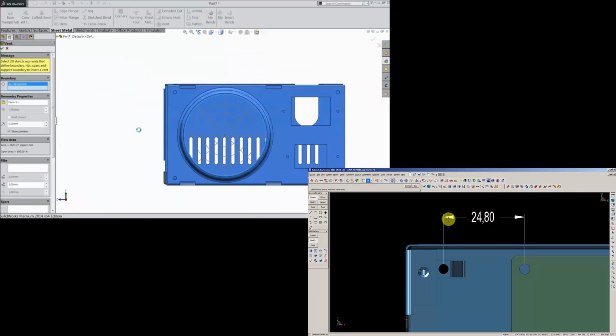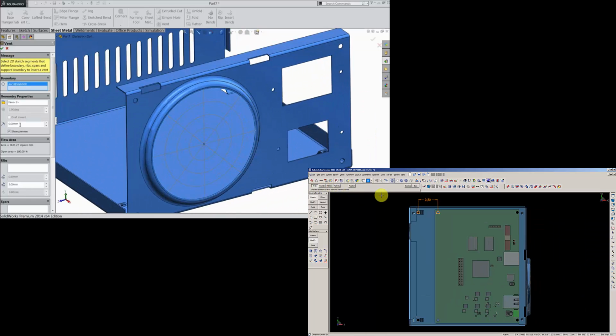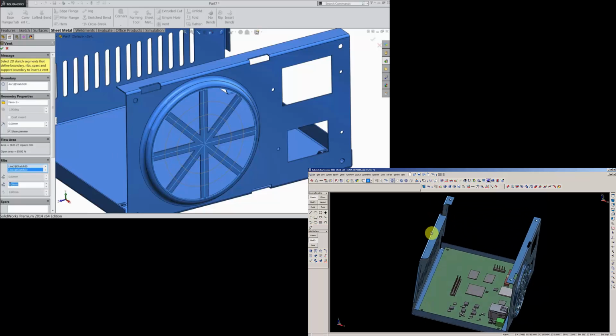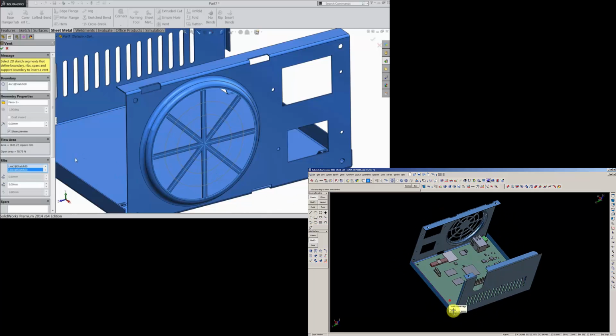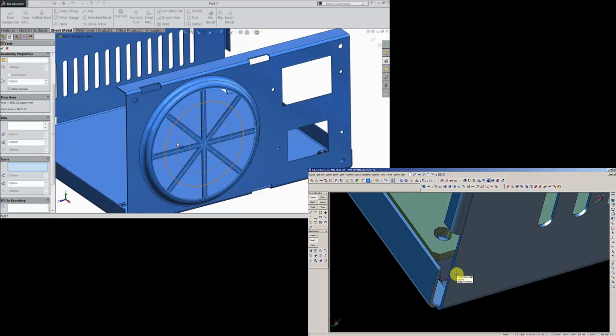select this outer line, select rib 1, 2, 3 and 4 and make the rib thickness 3 mm only. OK. Now select circles 1, 2.